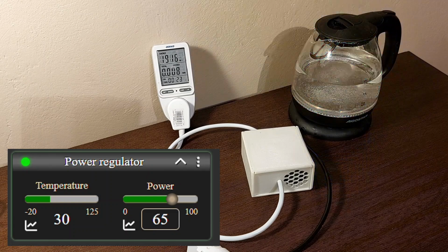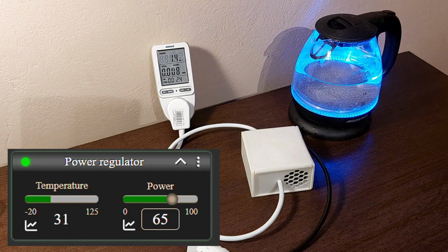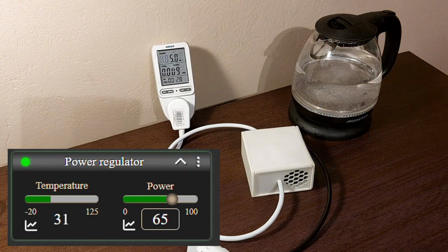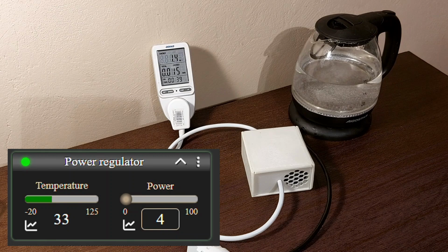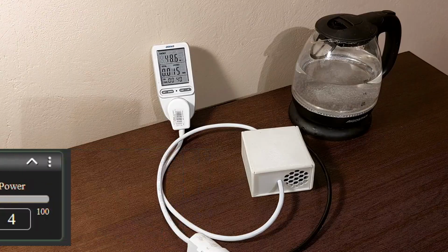But I guess I will find a better use for this power regulator. Also, cooling appears to be way above sufficient. Triac temperature rose just a few degrees above ambient, so I'm quite confident that it can also handle the full load of 16 amps. Great, no remarks to the hardware, time to start working on the temperature regulator.